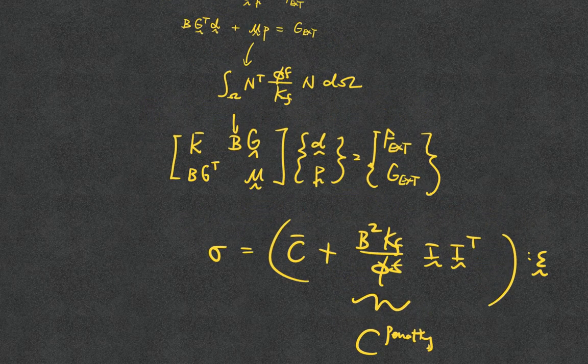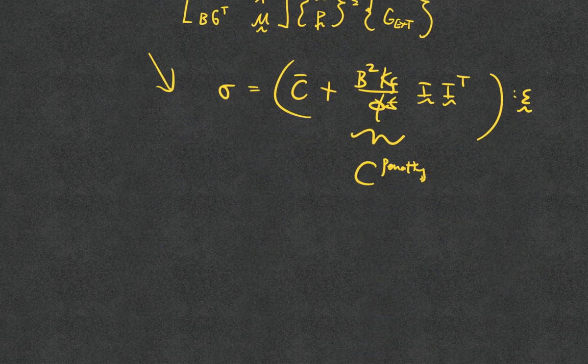Okay, so either choice will work, but they will work in a different way. Okay, this you have to deal with the inf-sup conditions. This one would look okay unless Kf is very big. Okay, if Kf is very big, what will be the issue? You may have locking. So, have you guys covered the volumetric locking in the finite element course? Okay, let me give an example here.